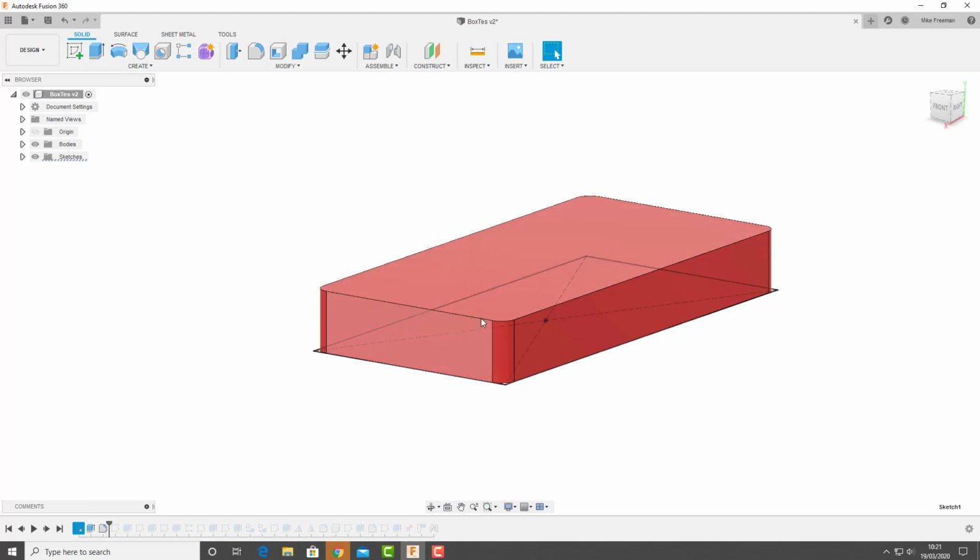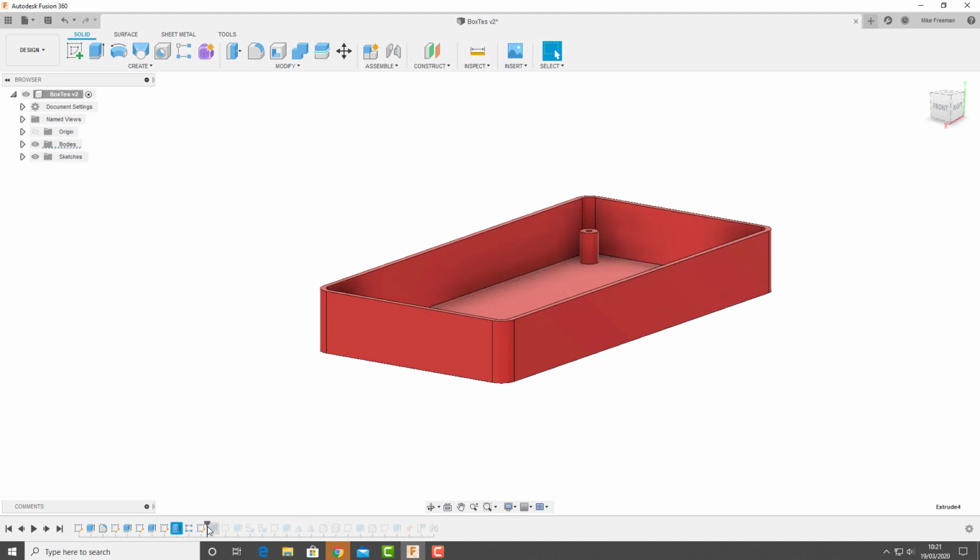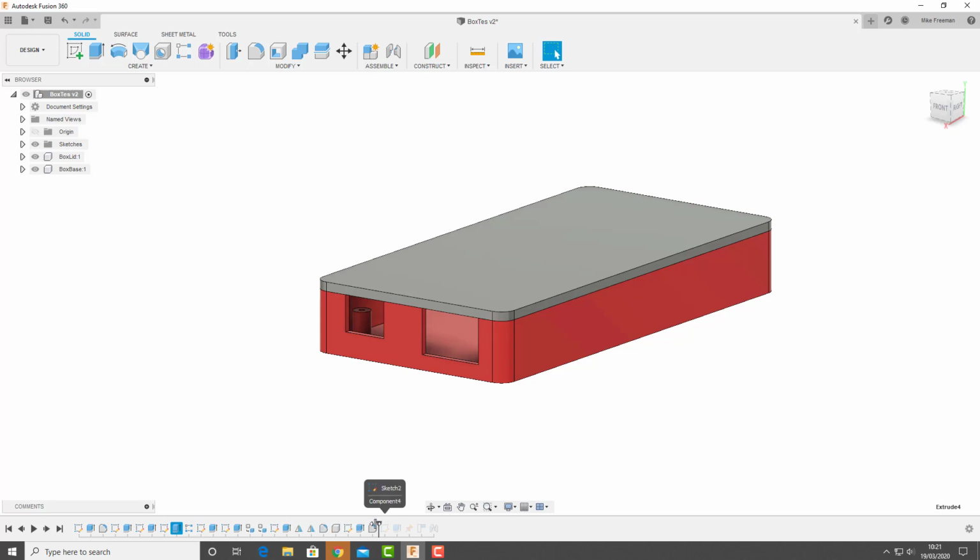We then rounded the corners of that box, the edges. We created another sketch on top, which was a smaller box, which we then extruded down to cut out the middle. We did more sketches, and we created the upstands, which we extruded, which you'll see in a minute. There we go. And we created holes in them, and then we made the lid and so on. So anyway, as you work, Fusion records this timeline, this design history.